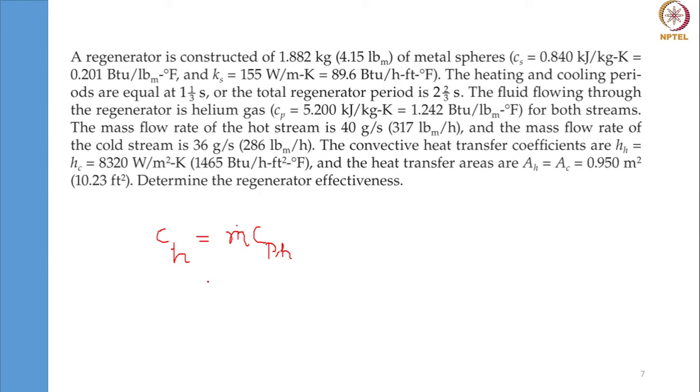So m dot here on the hot fluid is 40 grams per second, so 40 into 10 power minus 3 multiplied with Cp, which is 5200 joule per kg Kelvin. It is 208. Yeah, it is 208 watt per Kelvin.